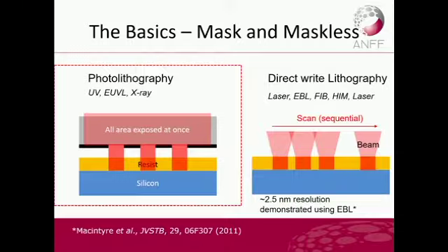But the laser mask writer that was covered this morning was also a direct write lithography. We don't usually use it for our microfabrication, apart from making masks in the clean room, because each time you make these wafers, it takes about 3 hours. So if you need to make 10 wafers, you need 30 hours. Whereas you can just expose the mask for 3 hours, and then you can produce each wafer in a minute or 2 minutes.